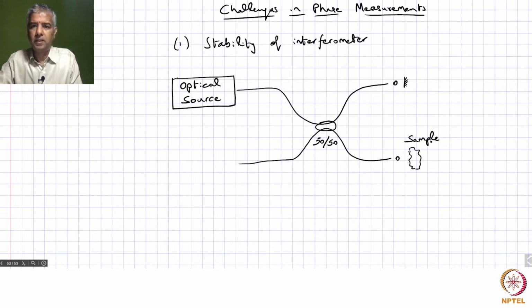In semiconductor processing, you want to understand the roughness of a wafer. You want to check the roughness of a wafer, and if the roughness measurement has to be made with, let's say, tens or hundreds of nanometer accuracy, you can put that through one of these interferometers, and all you do is translate the sample across.